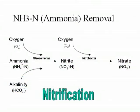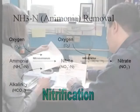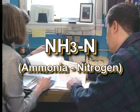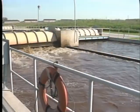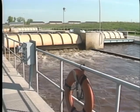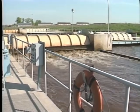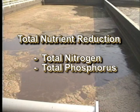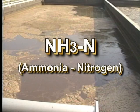In your NPDES permit, ammonia nitrogen is often abbreviated as NH3-N. Typically, treatment plants that have permit limits for ammonia nitrogen have a tougher job when compared to facilities that have no such limits. In some cases, treatment systems may also have nutrient limits, such as total nitrogen or phosphorus, that require even more complex treatment. Now let's take a closer look at ammonia.